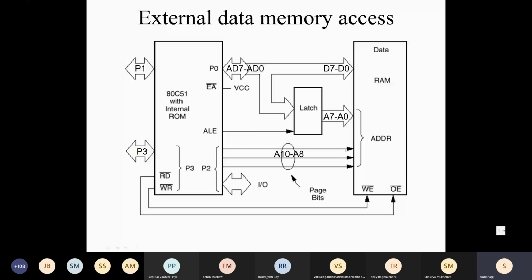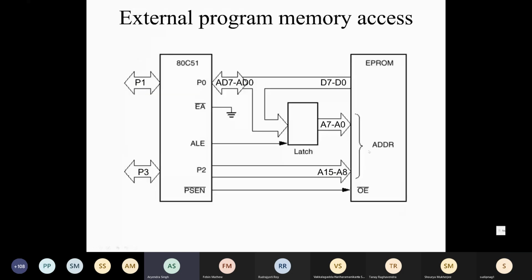Okay, another 1 byte, just double 1024 bytes, and so on. Yes, question. In the previous program, why have we connected the PSEN and programs to enable to OE bar, and what is OE bar actually? Okay, OE bar is an output enable bar, and PSEN is a program store enable, and this is again bar because active low. So OE bar is equivalent to an enable signal, output enable signal.